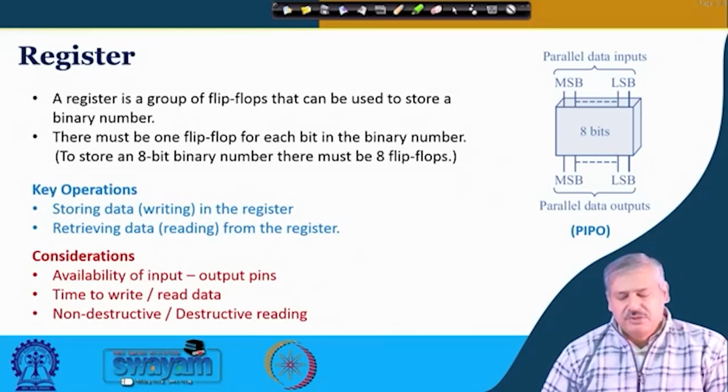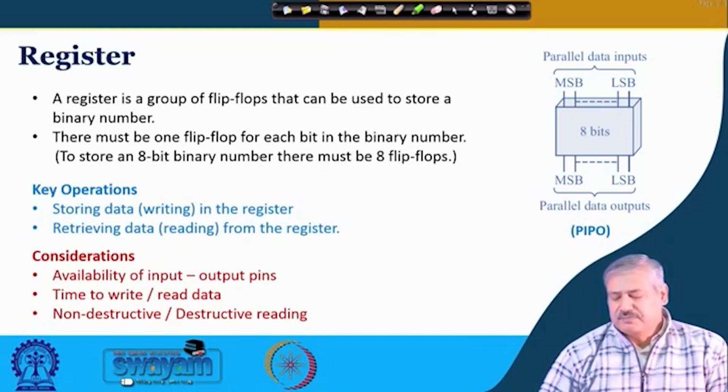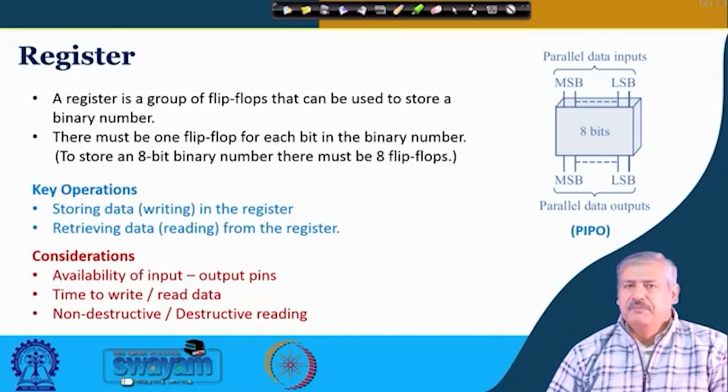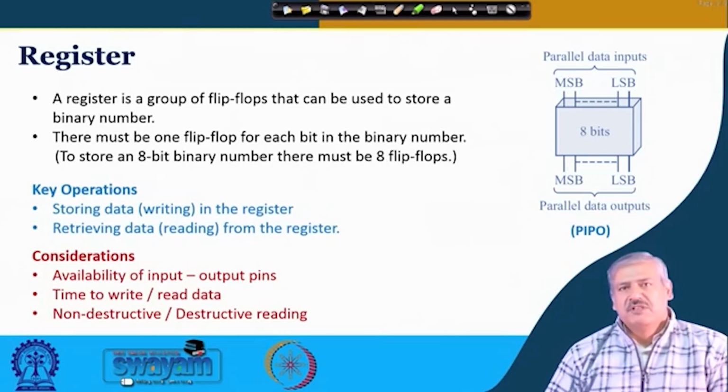Okay. So, for a 8-bit register, we will be having 8 flip-flops, and the way we have seen them, if we want to write something, that 8-bit information, and then read from it, then the way we have done it before, we can think of providing specific inputs to those flip-flops and then reading it from the output.